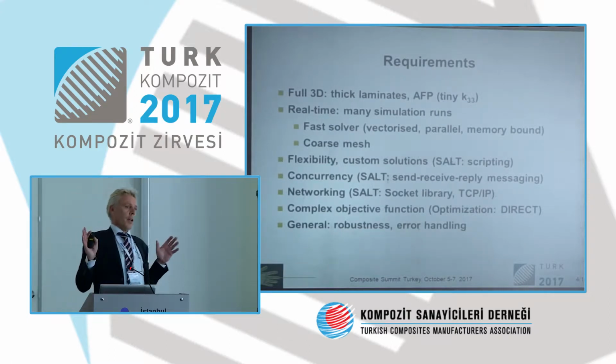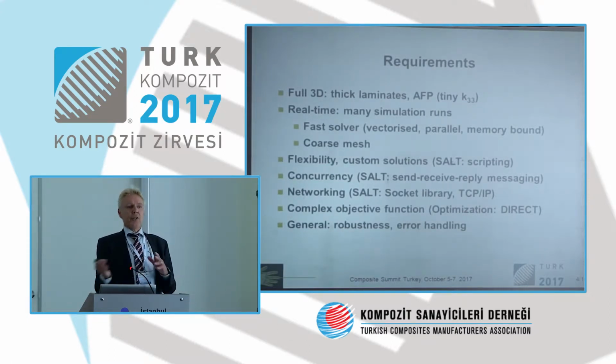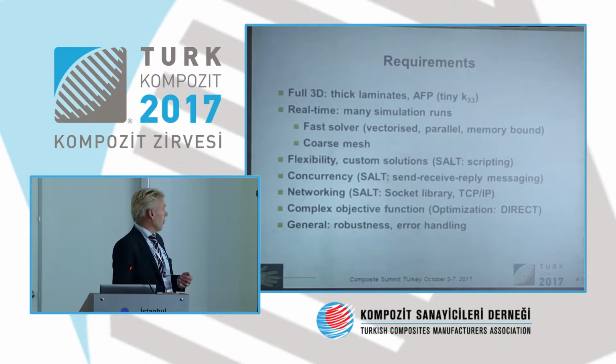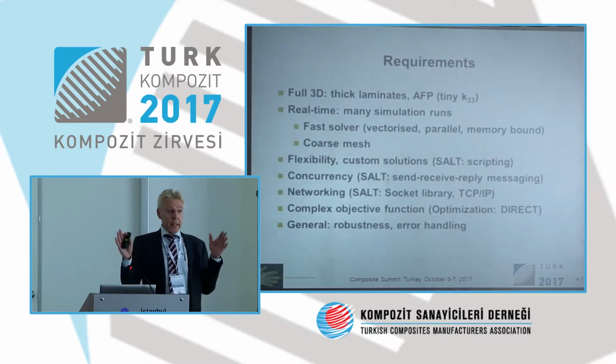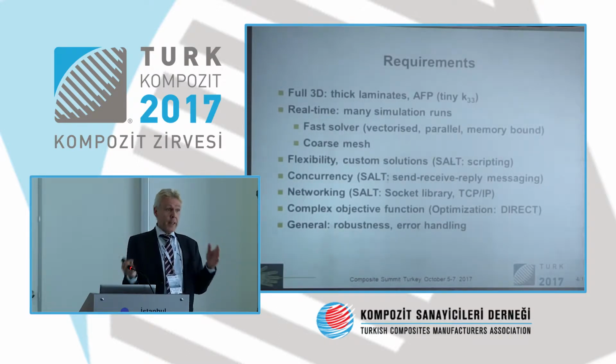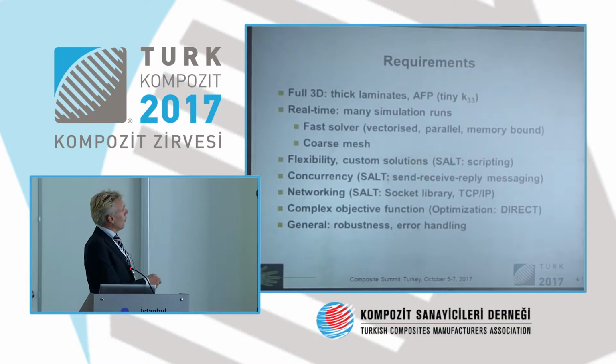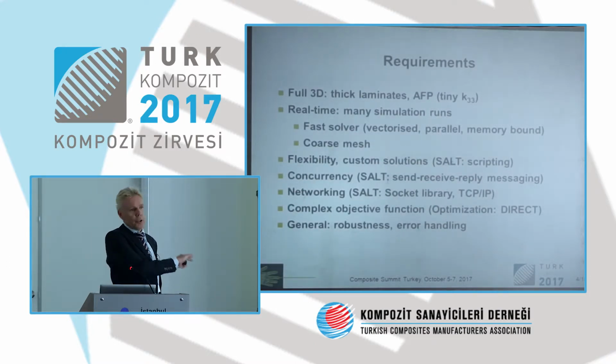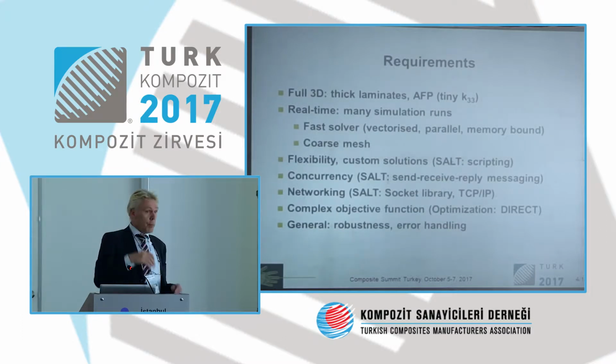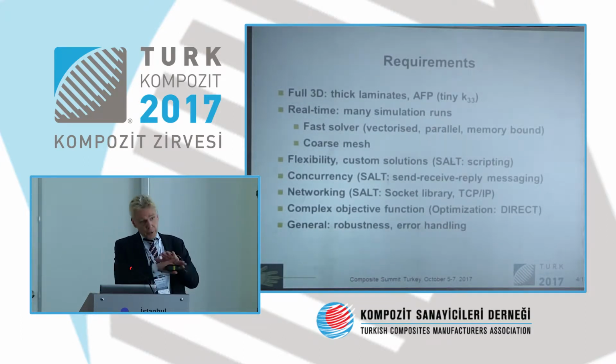Now, having flow analysis software and trying to link it to feedback from sensors, we wanted to do this in real time. So to have, actually during the injection, the feedback, match the model, and get a picture that shows what's going on. Now, first of all, we needed to do this in 3D. The example I just showed you, a 3D model, is from a tidal turbine blade. These are very thick laminates, so we need to model it in 3D. We also have thin laminates in aerospace, but with a very low permeability through the thickness. So actually, the surface fills very quickly, and then it takes a long time to go through the thickness. You have to model this in 3D, otherwise you don't see the details.